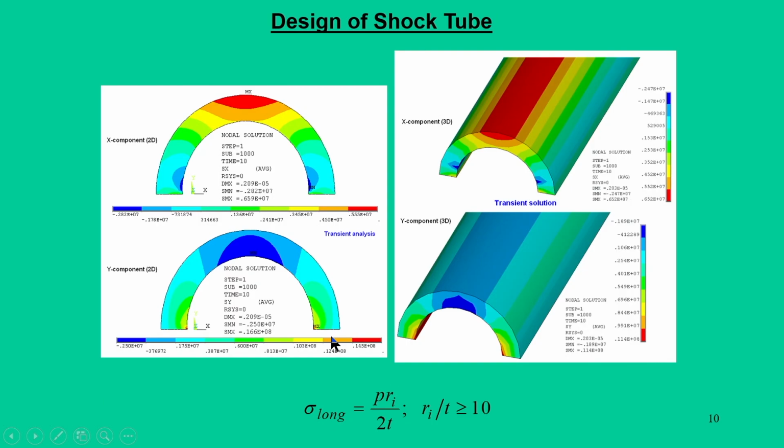By doing this, at the end of the day we are going to get the stress components at different locations. So, the cross section components, this is lengthwise. If you take a stainless steel material, and this particular analysis can also be carried out with different materials, typically stainless steel is a favorable material to withstand very high pressure.